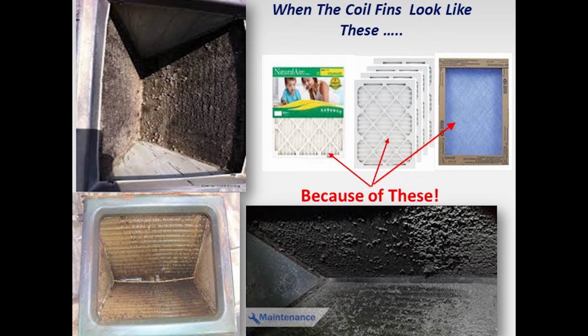So the MERV rating, MERV 11, MERV 13, what have you, only speaks to its ability to trap particulate of a certain size range. It has nothing to do with longevity of life or how much dirty air can sneak around that filter.